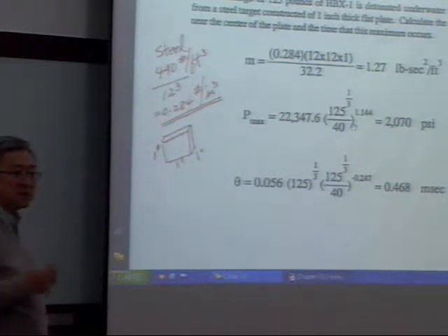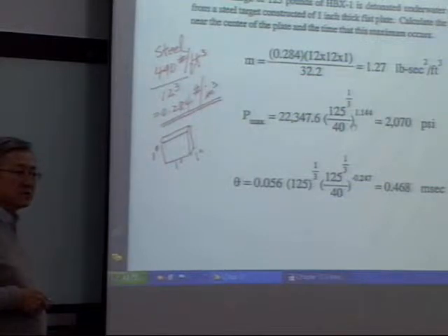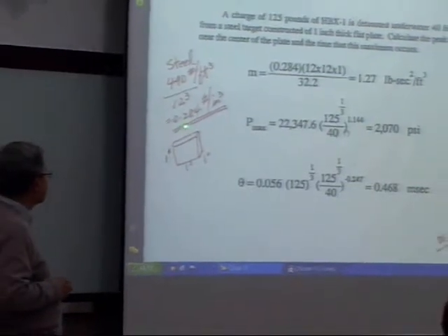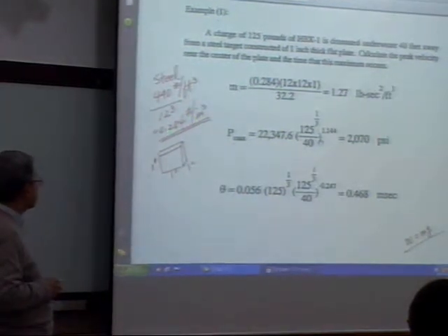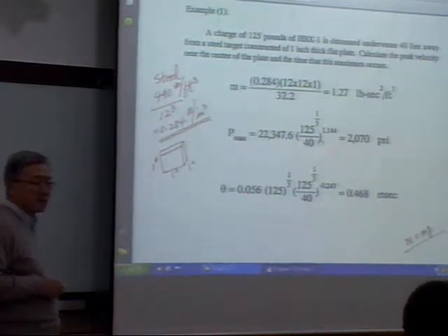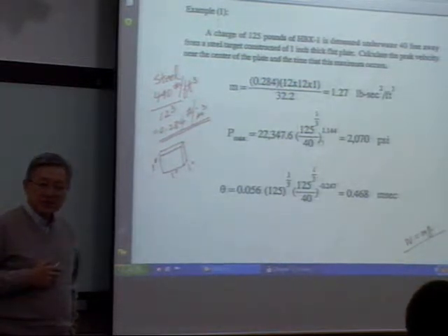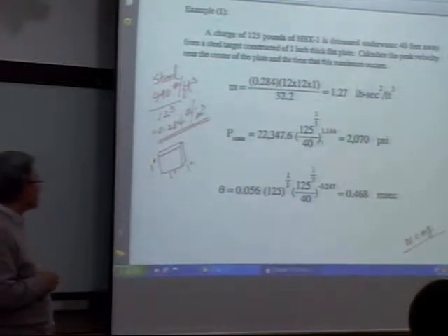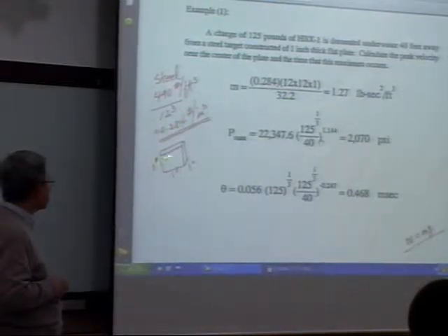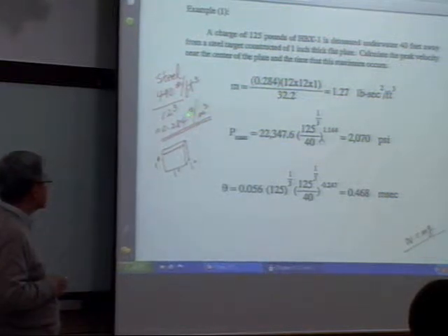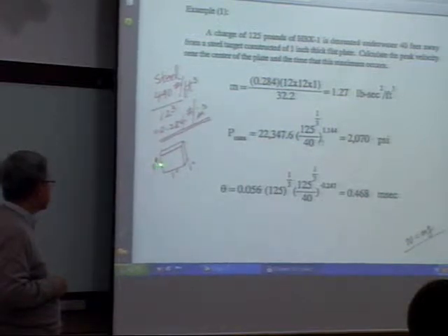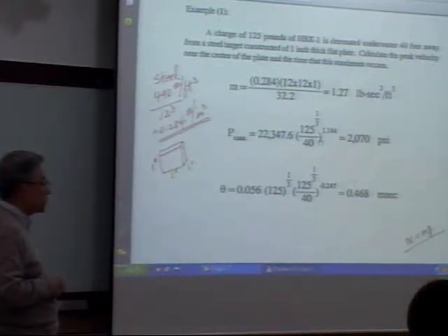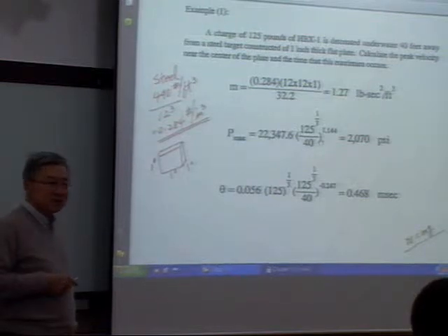When you screw up, you end up getting the wrong solution, wrong thickness. So convert into pound per cubic inch is 0.284. That's the weight density in pound and inch unit, 0.284, which is the weight of general carbon steel for 1 inch by 1 inch by 1 inch cube.